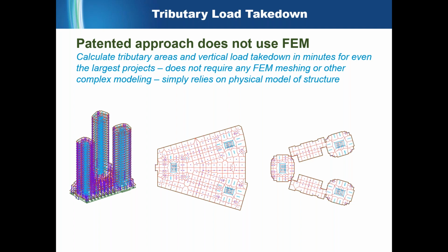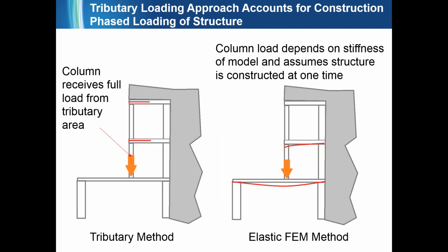It does not require any kind of FEM mesh or analysis to be completed, and in fact that's one of the benefits: you can do a tributary analysis before you have a finite element mesh or solution, so it's much faster and more forgiving. It can also be more correct. So let's just use this as a quick example.